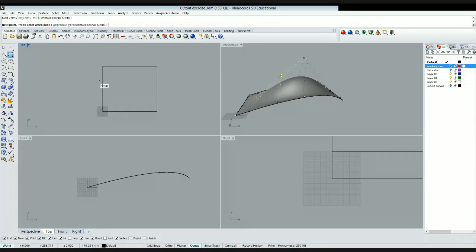Click here, 2, 3, 4, 5. Okay. So now I will turn on my control points and I will move this point with the move command and with ortho a bit more, so it's close to my edge. Okay. Escape to deactivate the control points. And now this is my shape that I will select by pressing Shift, all my lines, and I will join them.